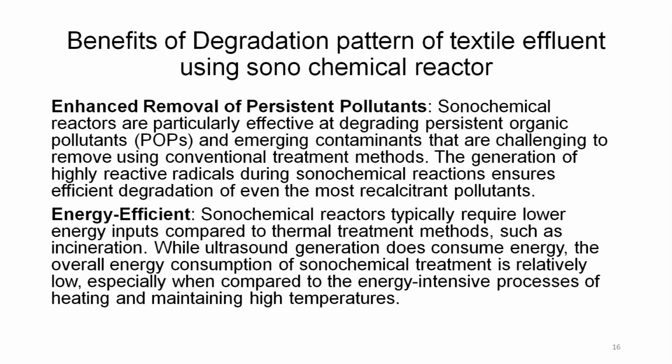Energy efficient. Sonochemical reactors typically require lower energy inputs compared to thermal treatment methods such as incineration. While ultrasound generation does consume energy, the overall energy consumption of sonochemical treatment is relatively low, especially when compared to the energy intensive processes of heating and maintaining high temperature. So, here the overall energy consumption also is low, because the sonicator works at a very low voltage, but it generates ultrasound waves, and it is these waves that are actually responsible for making bubbles and the cavitation process of generating these bubbles which grow up and which eventually explode violently.